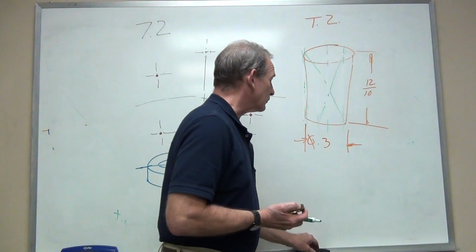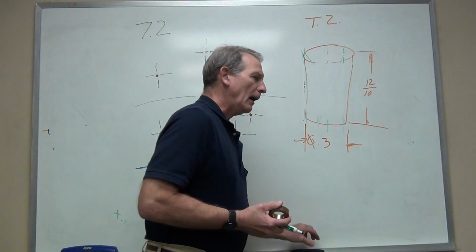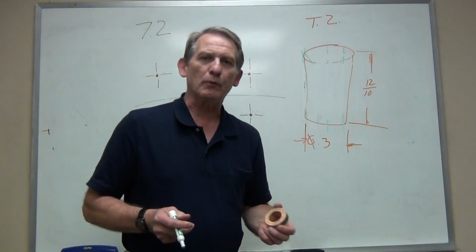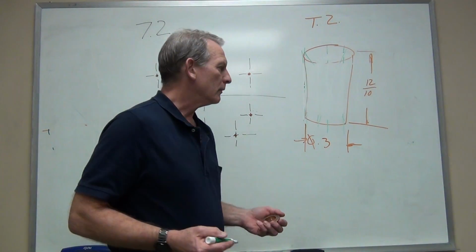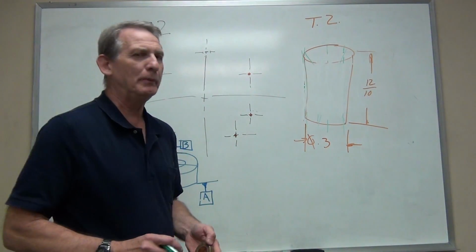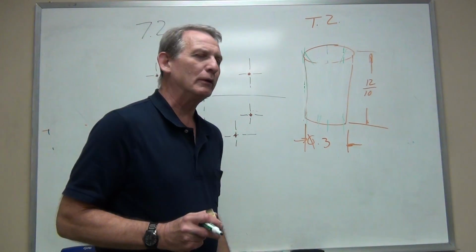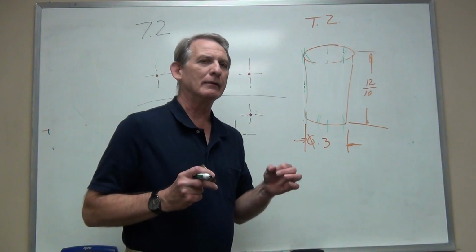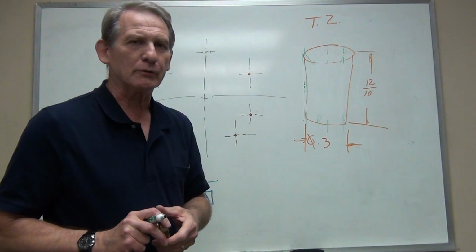And again, since there's nothing else to tell me otherwise, I also have a form issue with the hole. Now, what can go wrong with the hole? The hole is intended to be a 3.32 millimeter diameter cylinder, and so it should be cylindrical.